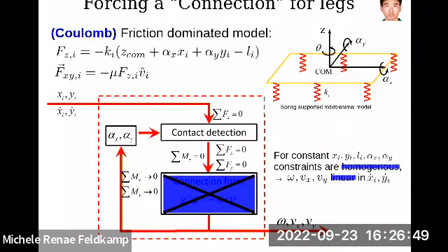If all my legs are on Coulomb friction, it will work. If all in viscous friction, it will work. If all in dynamic Coulomb slipping, it will work. It's just when some legs are doing one thing and some another that it won't work. So this is pretty robust to changes in the kind of friction, is the short answer.